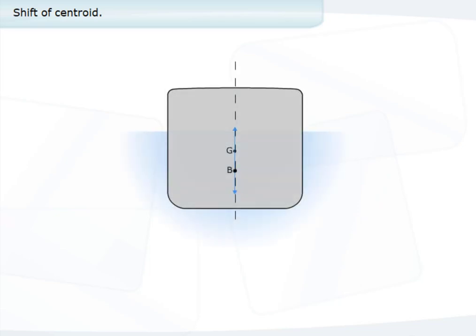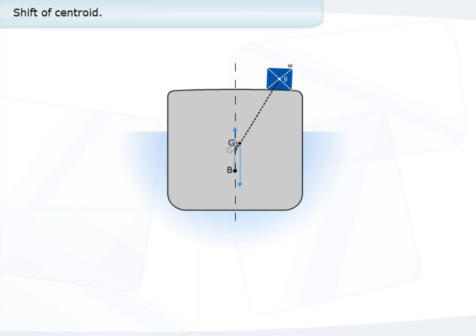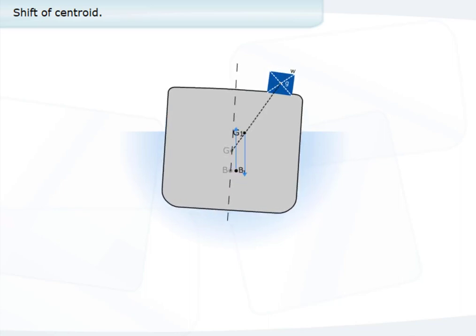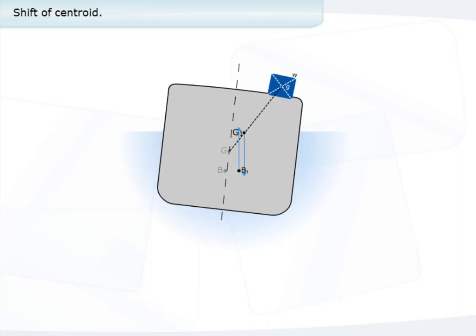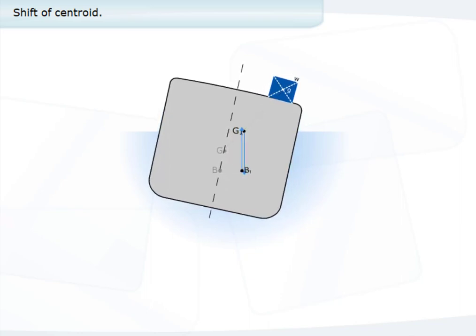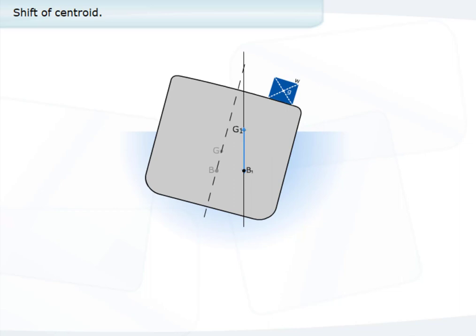When a weight is shifted on board, loaded onto or discharged from a ship, the original centre of gravity of the ship will move parallel to a shifted weight, directly towards the loaded weight, and directly away from the discharged weight. On a ship working cargo, this will normally result in the centre of gravity G moving at an angle from the centreline. To make this easier to calculate, the movement is normally broken down into two parts, the horizontal movement and the vertical movement.